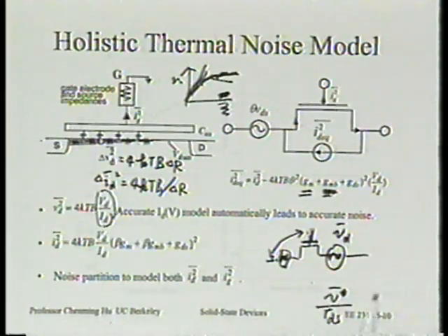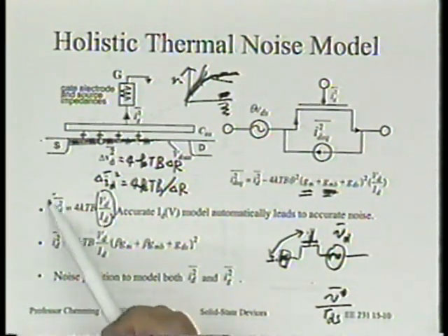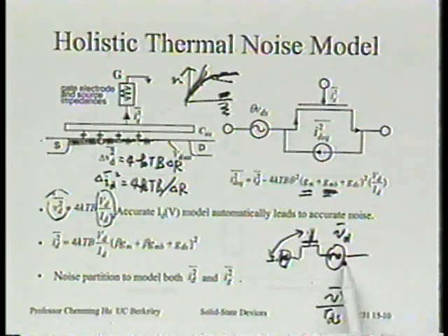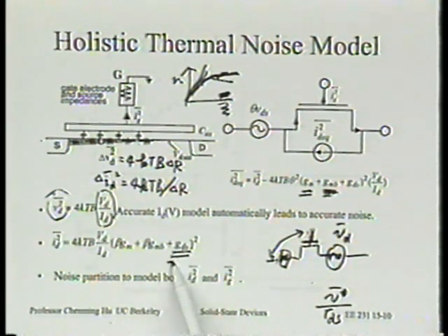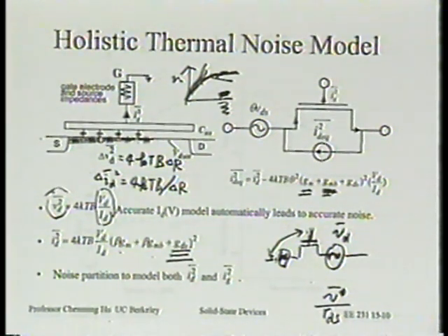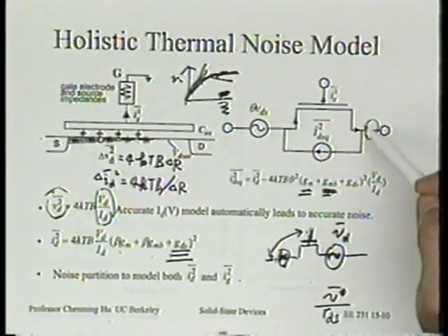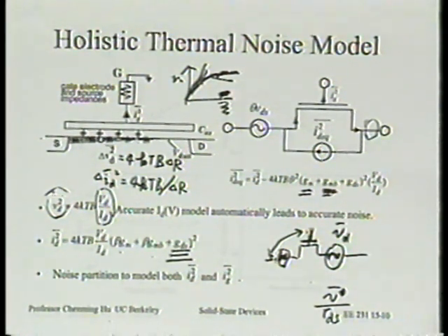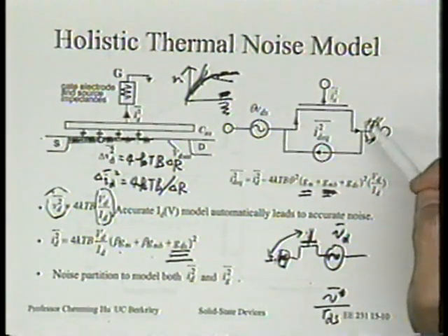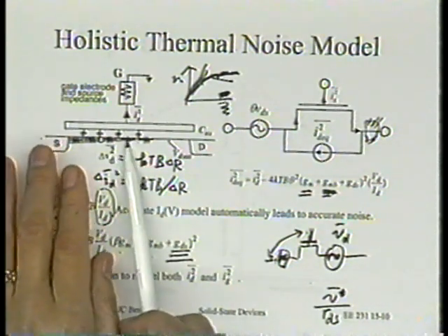So we know, it doesn't matter what fraction of this noise source we put on the source side or drain side, both of them will be translated into current through GDS. But only the fraction put on the source side will get amplified by GM and GMB. Is that right? The part on the drain side will not be amplified by GM or GMB. So beta is just the fraction that should be amplified.